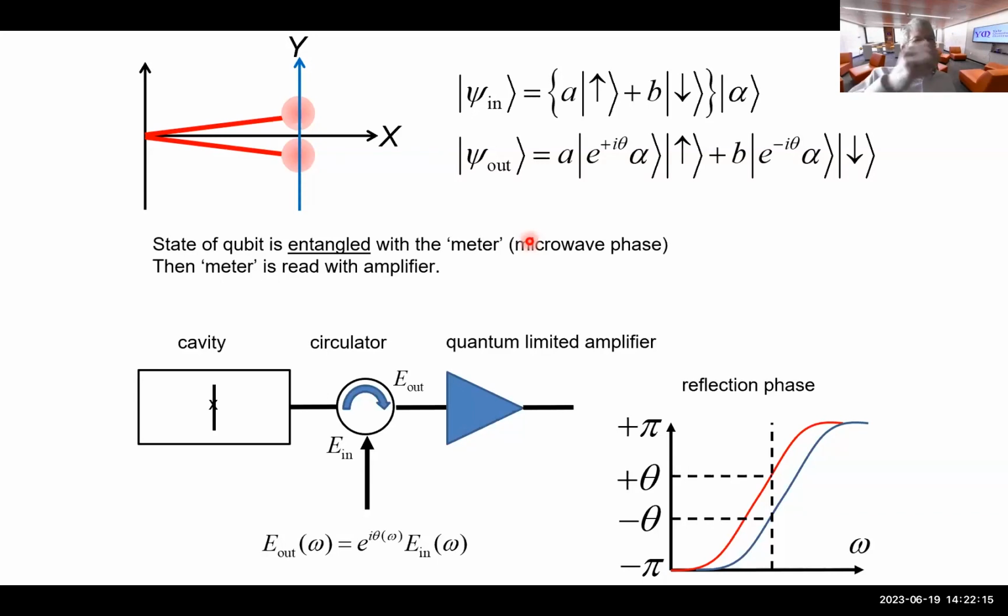You'd like to have a pump that pumps in not 1 photon at a time, the way a signal generator does, but 2 photons at a time. And the way you do that is you take 2 pump drives that are both off resonance with the cavity, one below the cavity, one above the cavity, and you pump that transmon with them.